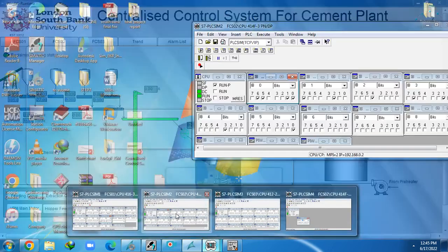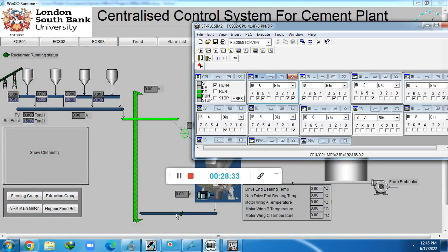Now this time I'm going to give a control signal there, which is reject elevator DE01 state, 1.3. Once done, it will wait for 5 seconds. It will start the second motor, which is this one and that one, belt conveyor 1 and belt conveyor 3. So belt conveyor 3 is started. Belt conveyor 3 is 2.0. Done. Once done, belt conveyor 1 is started. Belt conveyor 1 is 2.5.